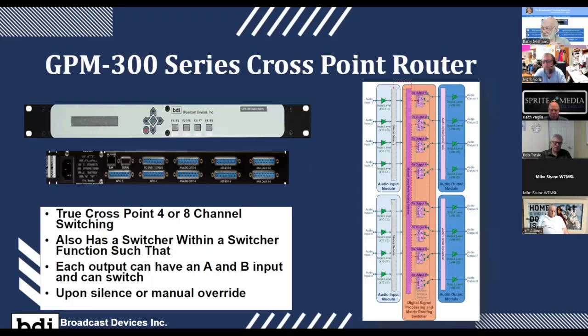So we can interface directly with a serial connection to these various EAS systems, which makes it kind of handy. And then what happens is our unit becomes a slave to the EAS unit at that point. You configure your EAS unit for whatever your operation is, and it'll select those channels. Now, for Sage, they only allow you to do up to 4, 3 external, 1 internal. So it'll control 3 channels on our unit. And I think DASDEC, at last check, did 5. So if you need to have that many, you'd order an 8-channel unit from us, and you could cover up to 5 stations.